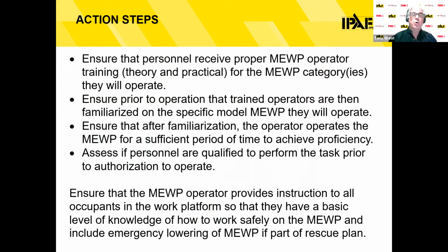Well, again, we need to ensure first that all of our personnel receive proper MEWP operator training, which includes both theoretical knowledge and practical hands-on operation for each MEWP category that you will expect them to operate. They need to be familiarized on the specific model machine that they're going to receive or be expected to operate. And once they're familiarized, the operator must be able to operate that different model for a sufficient period of time to achieve proficiency before he begins doing the task. And they need to be assessed as qualified to perform the task prior to authorization to operate.